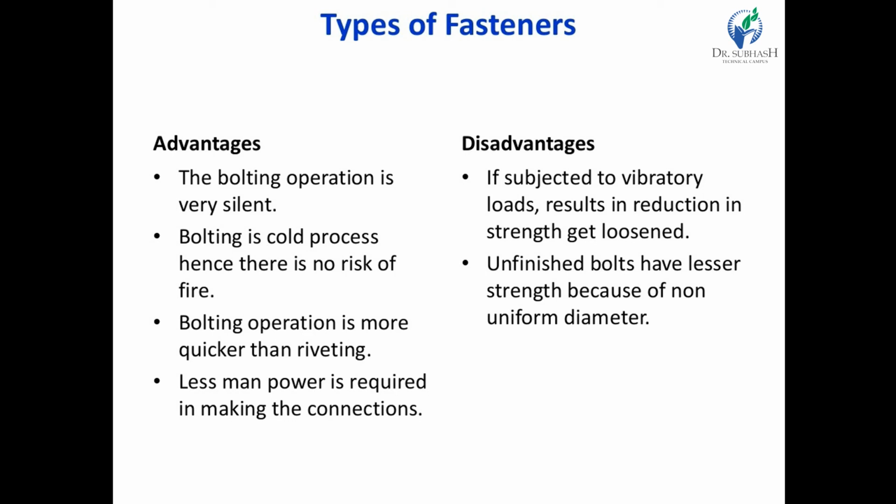The bolting operation is very silent. Bolting is a cold process, and hence there is no risk of fire. The bolting operation is quicker than a riveted connection. Less manpower is required to make this connection. Now what are the disadvantages? When subjected to vibratory loads, there is a reduction in the strength of the bolt. Also, unfinished bolts have lesser strength because of non-uniform diameter. So these are the disadvantages of bolts.